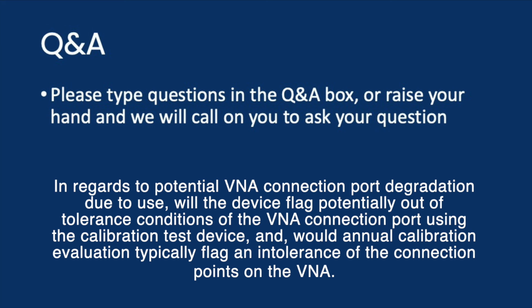We do have some new capabilities that we're introducing on our VNAs that allow us to actually compare results after calibration with the actual characterization information of the standards. So for instance, on our cal kits, particularly our manual cal kits, it comes with S parameters for each one of those standards, the open, the short, and the match standard.